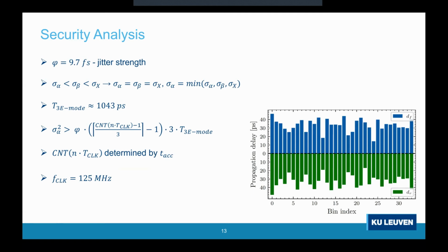entropy. Okay, now we have a stochastic model, we have our TRNG design, we implement our design on FPGA, and we calculate the so-called platform-specific parameters. So we can calculate the mean entropy estimation by using the formula in the previous slide. First, platform-specific parameter of importance is the jitter strength. The jitter strength characterizes the increase of the Gaussian jitter variance with time.